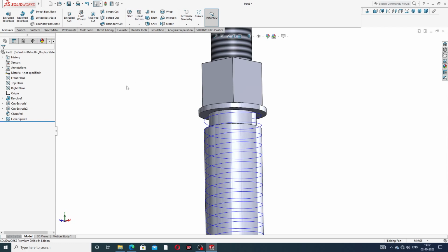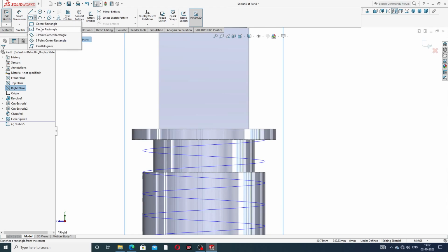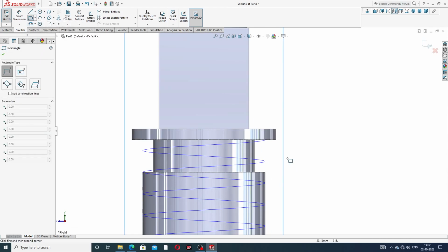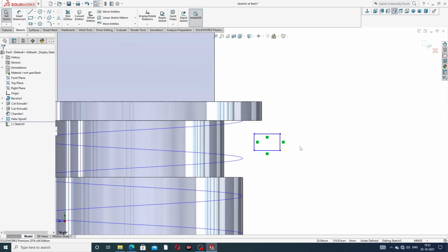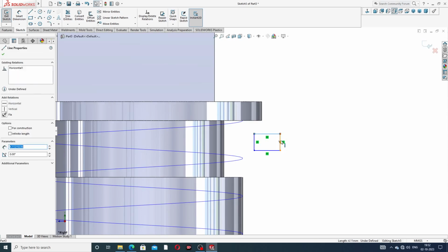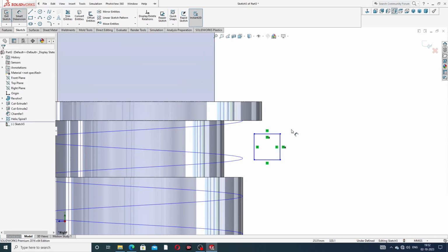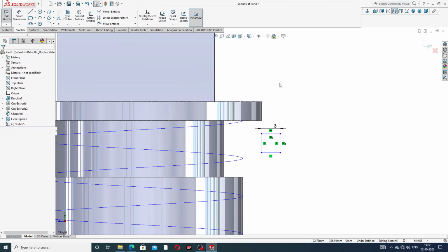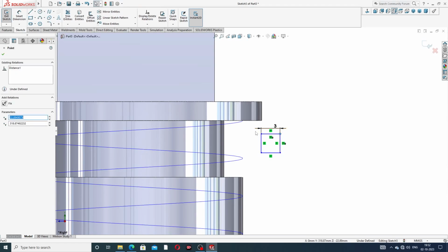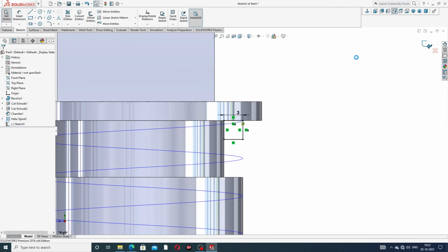Okay, and use the right plane, sketch normal. Draw a corner rectangle. Select both lines here and make them equal, and use a dimension of 3 millimeter, which is perfect. All is correct. Select this point, press the Control button, select this line, and use Pierce. Okay, and exit.